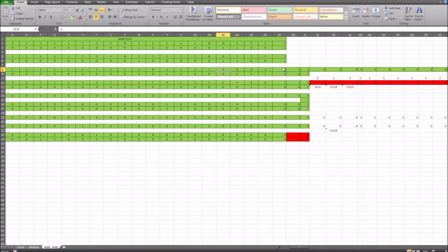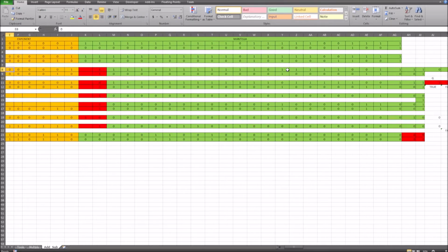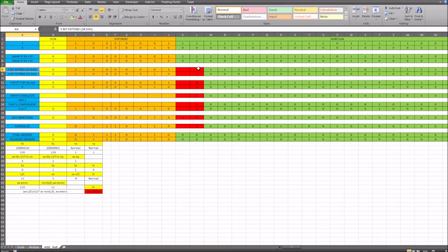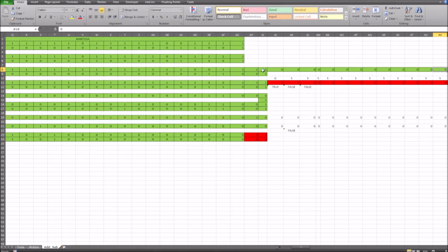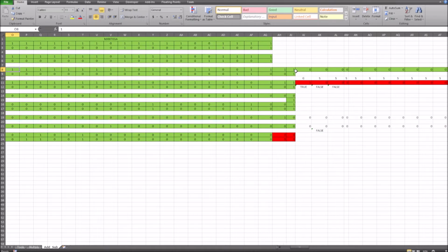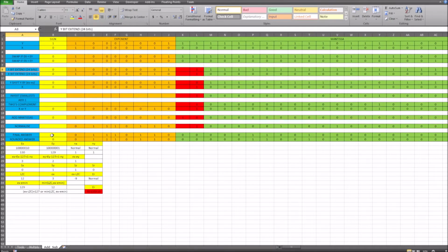If the exponent difference is a value of 1, again it means that we're going to shift the y value over by 1, but shifting it by 1 will only enter one value in here, and that will be the guard bit. We won't have any information for the rounding bits. It's not that the rounding bits are all zeros or all ones or something in between, we just don't have any information, they don't exist. So therefore we don't need to progress with the rounding on the near path.